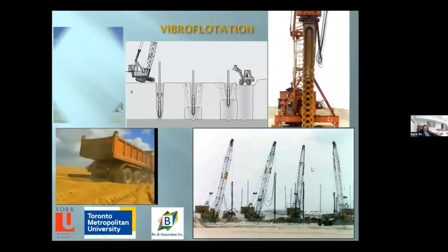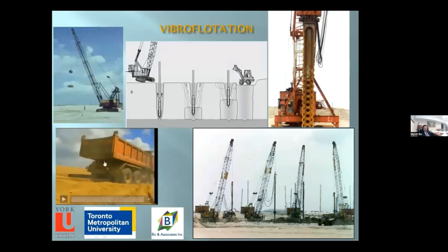These land reclamations deposited granular soil loosely, and then they are prone to liquefaction, and they also generate immediate settlement. In order to eliminate these, the thickly deposited reclaimed land has to be compacted using the compaction methods called vibroflotation, dynamic compaction, and resonance compaction, etc.